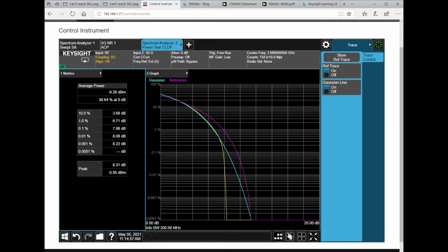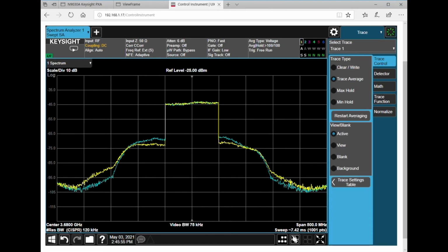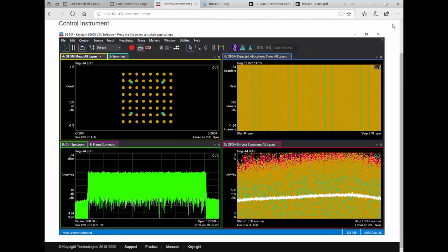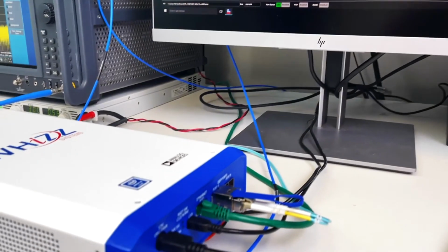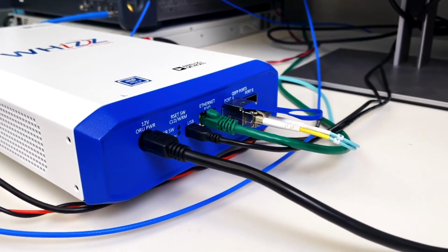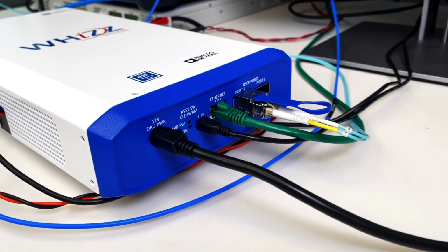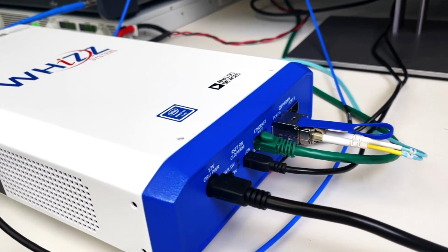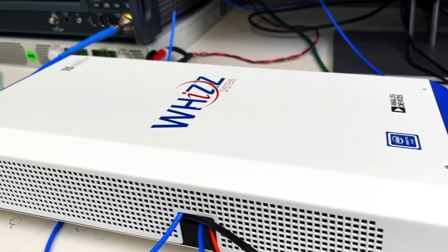This allows us to operate the power amplifier in a more efficient region closer to its OP1dB, thus saving on power. The distortion generated by operating the PA near saturation can be corrected by the integrated digital pre-distortion engine in the ADRV9029. Together, the CFR and DPD engines provide in-band flatness, spectral emissions, ACLR, and EVM improvements for the transmitter. This O-RU reference platform is just one of many from Analog Devices that cover FR1 and FR2 bands, ranging from small cells to massive MIMO configurations.